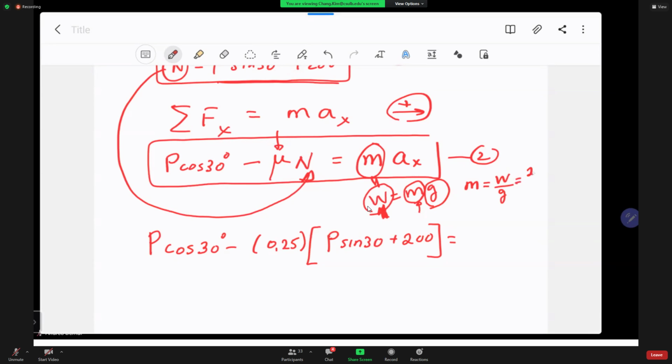The weight is 200 pounds divided by 9.8, so that's going to be 200 divided by 9.8. Now the acceleration, we want to accelerate that. This is in pounds, so sorry about that, be careful and don't mix that up. I need to use 32.2 instead of 9.8. So 32.2, and this would be 10 foot per second squared. So watch out for the units.